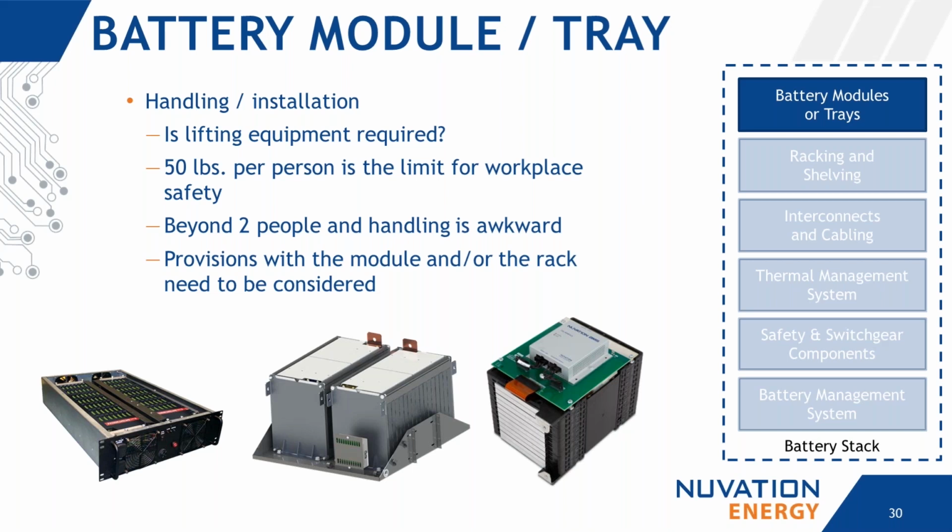And then beyond 2 people, handling a battery starts to become a pretty awkward scenario. So in many cases, that means once you're past 100 pounds, which is not too uncommon for a battery module, it's quite likely that lifting equipment will be required. In that case, provisions with the module and/or the rack need to be thought through, which is much easier to do earlier on in the design.